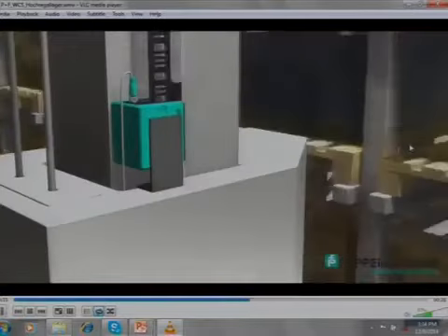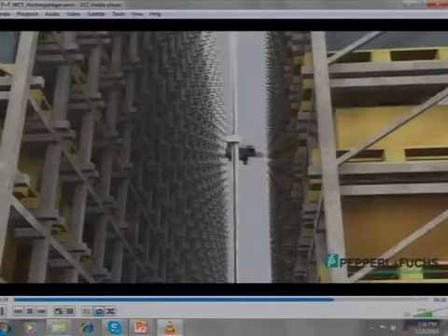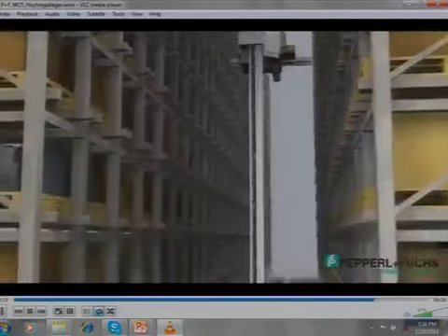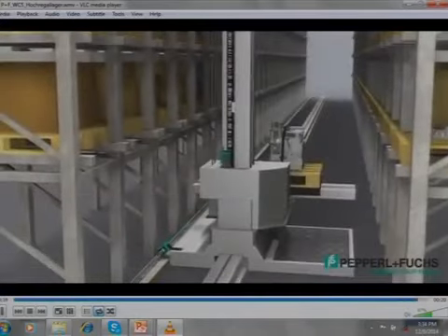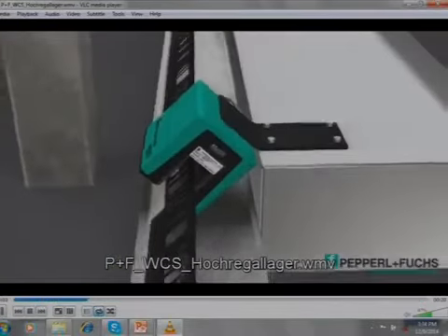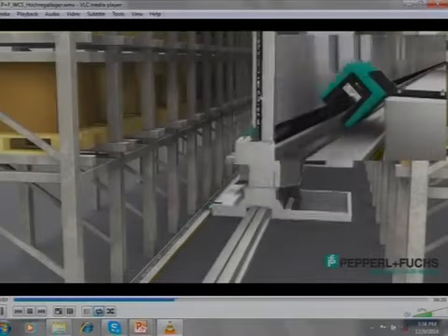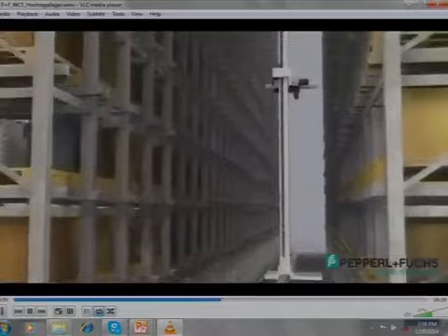And just on the output part, because of the PLC. Okay. Now, because this is giving the positions, it cannot be a digital output. So it is on the communication bus. The communication can be RS485, Profibus, DeviceNet, Ethernet, any type of network, and we get an output on this device.